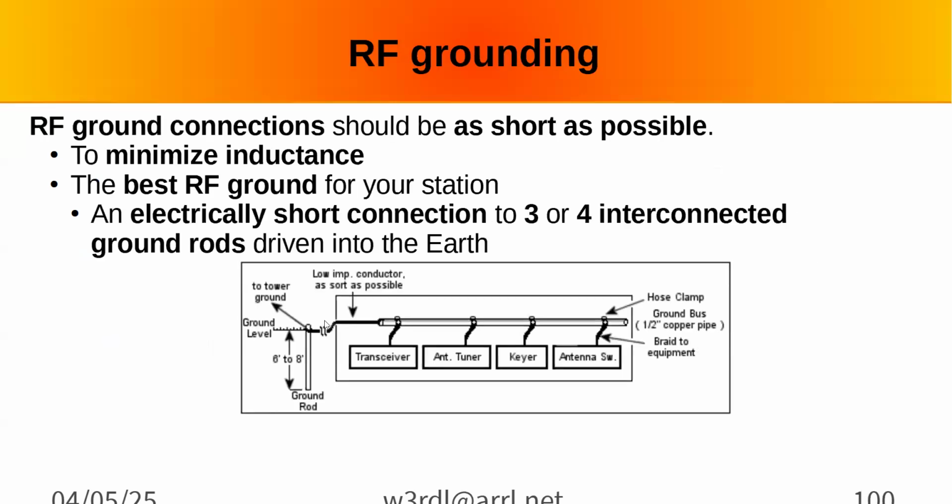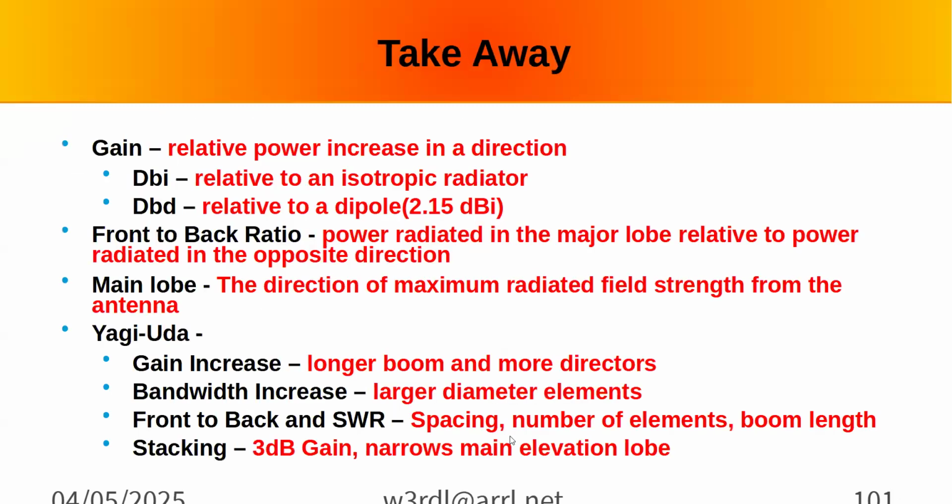And this is showing a typical setup where a lot of times they'll mount, I think that's what you may have right in the shack, copper pipe. Some copper pipe bar or something. Yeah. Typically they mount a piece of copper pipe and then tap everything into it and tie that to an external ground or grounds.